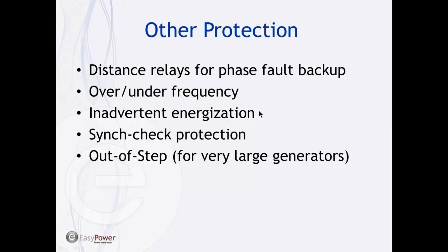Over/under frequency, again, this is going to be tied to your volts per Hertz, but also your interconnection requirements. But obviously there's going to be limitations on the frequency range that this system can operate at, but normally your grid requirements are going to be more severe than the actual machine limitations.